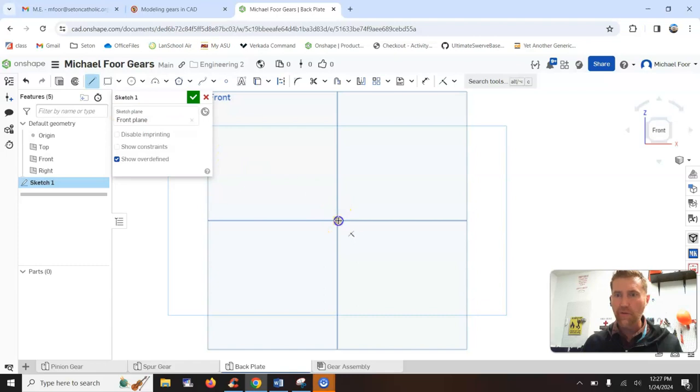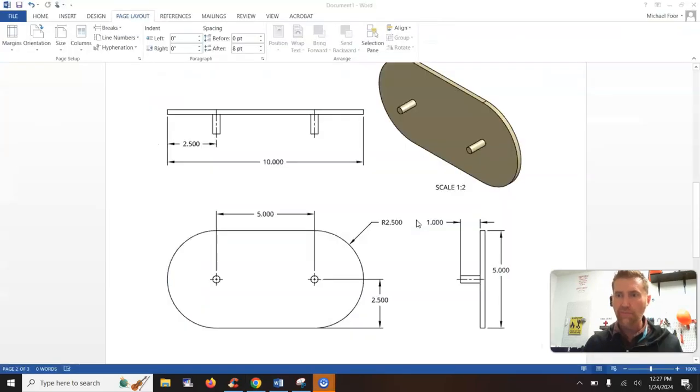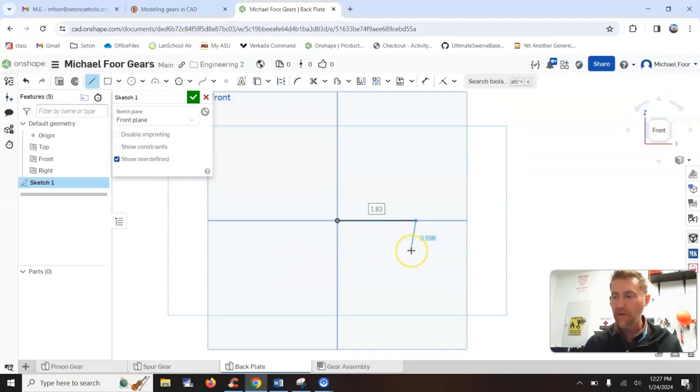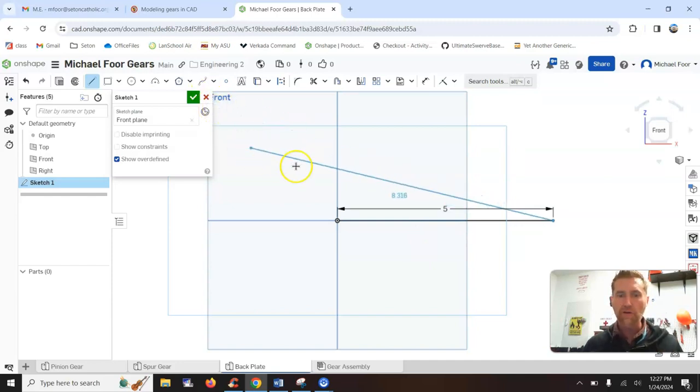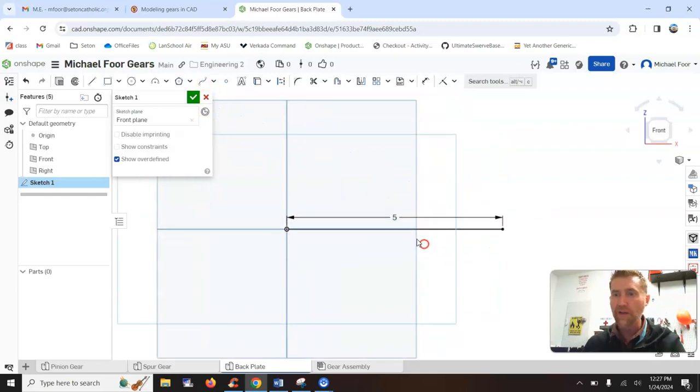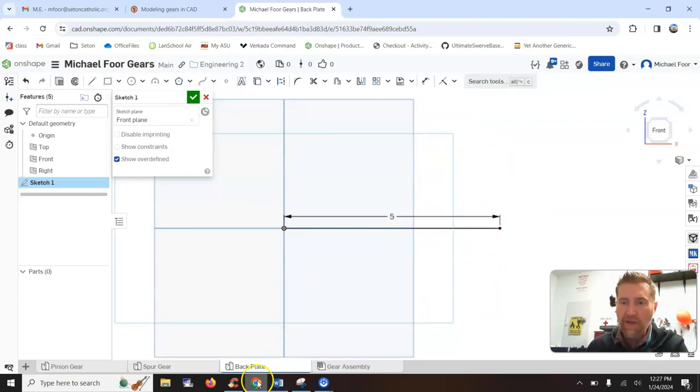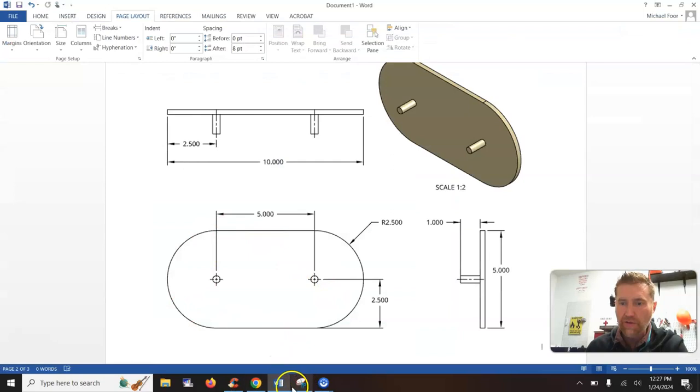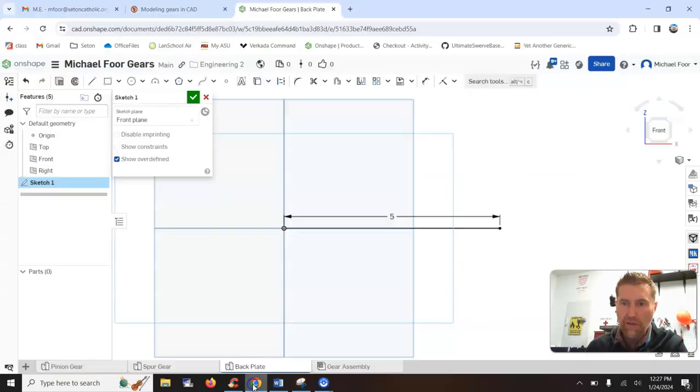And I'm going to start with the origin, and the 2 posts are going to be 5 inches apart. That's where the gears are going to mount. Where does that 5 inches come from? That's the distance between the 2 bores on the gears that would have them still mesh. Okay, so we got this distance here. Now I'm not going to finish the sketch, and I'm actually not going to draw all this circle bit around. Let me show you a sneak ninja way to do this.